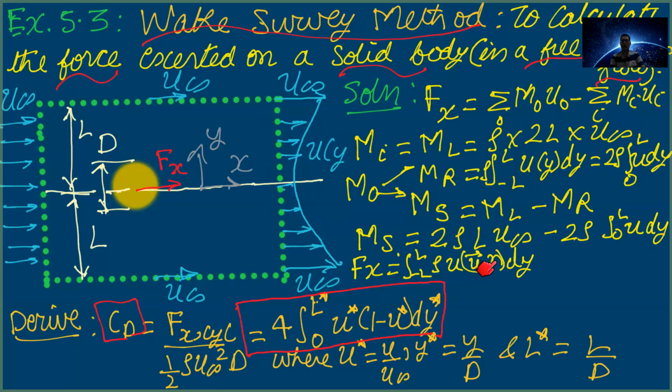So this u dot n is also a velocity in the horizontal direction. So this will become rho u square dy. Right now it is minus L to plus L rho u square dy, but later we write it as twice the integral of 0 to L rho u square dy. So this is the momentum flow rate leaving from the right wall.